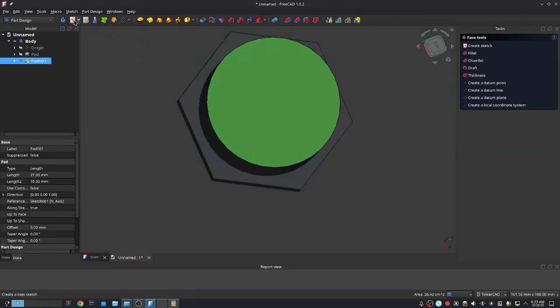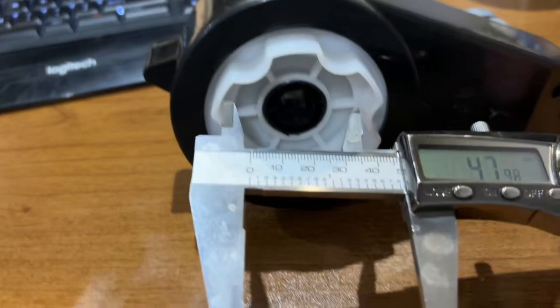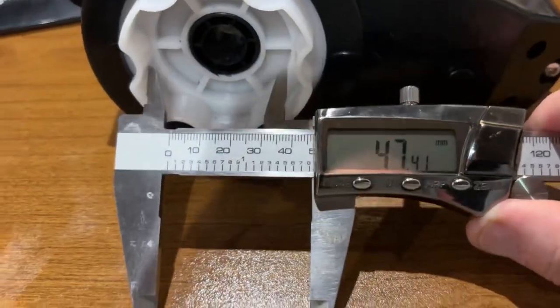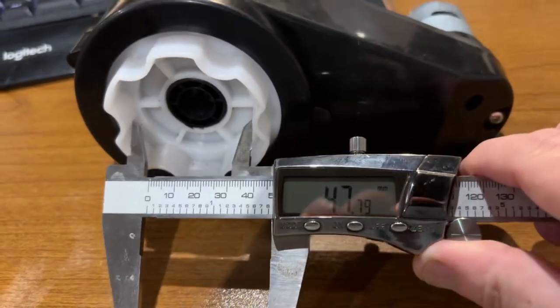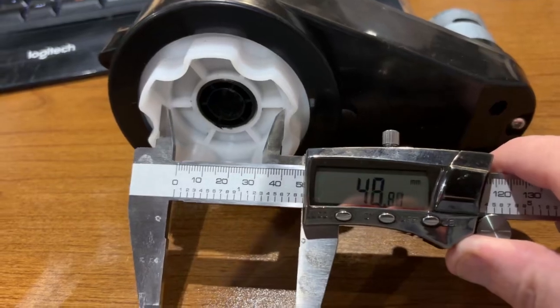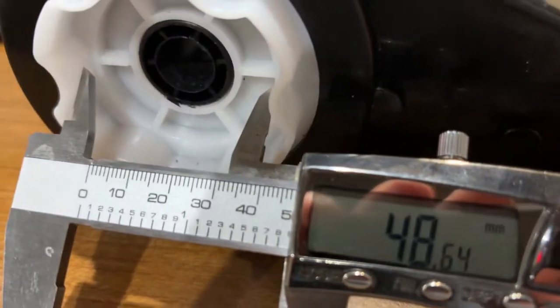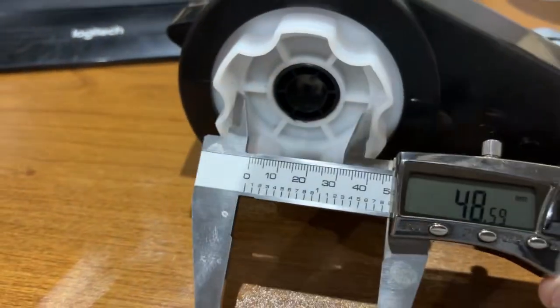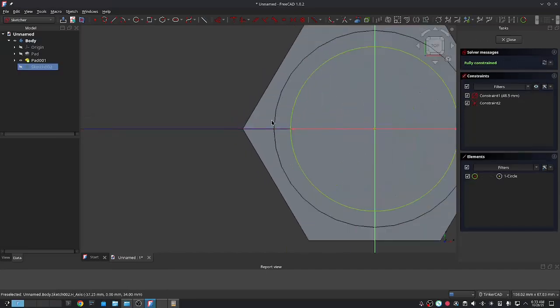We'll click this surface. We'll start a new sketch. This is going to be a construction line, really. Especially one handed, it's hard to get a good measurement on that inside. It looks like we're going with, I'll do 48.5. Circle. 48.5. Do another circle right here.